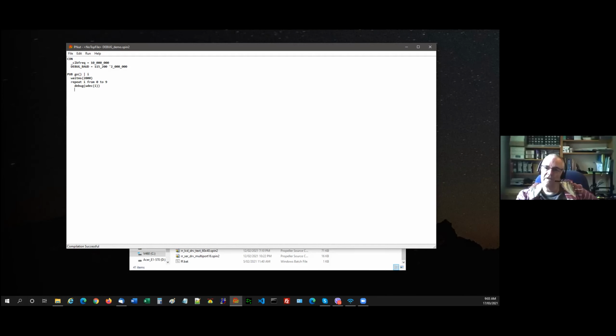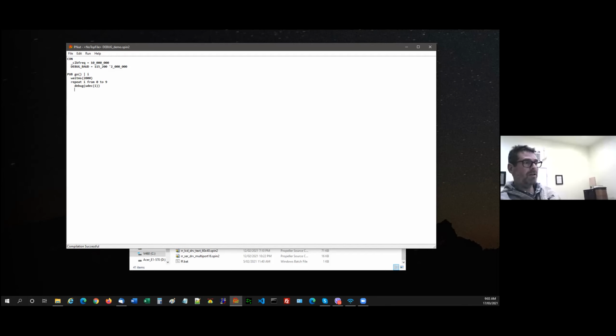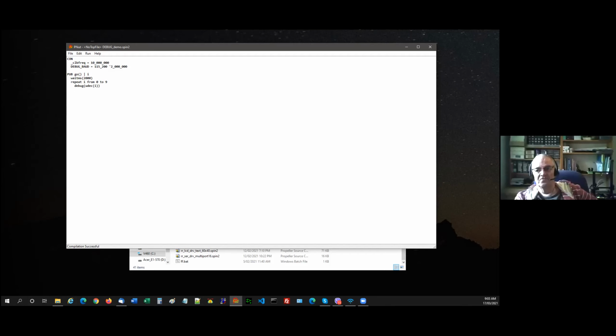You configure it because you talk to a USB chip from the PC, and you tell it to change speed. Now you do the same thing to a CP2102. Now Load P2 can change my load. I can load into my board at 115200, or I can load it at 2 megabaud on the CP2102. So if you're doing something specialized for an FTDI chip, you're going to need to be generalized rather than specialized.